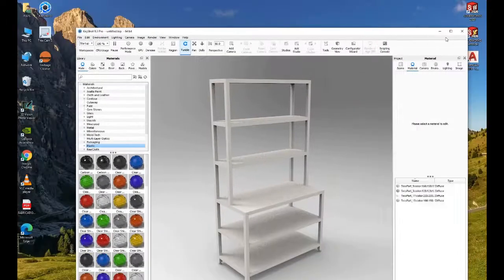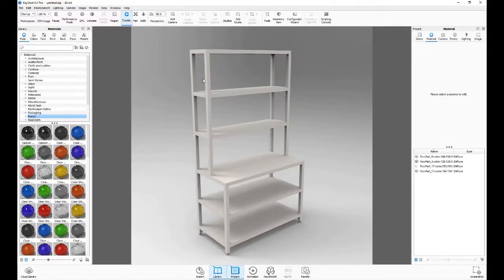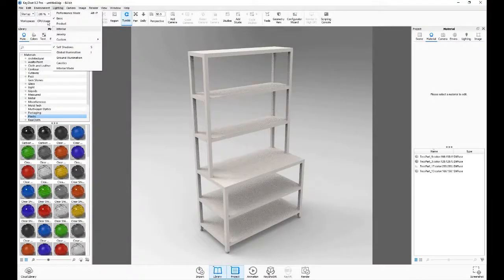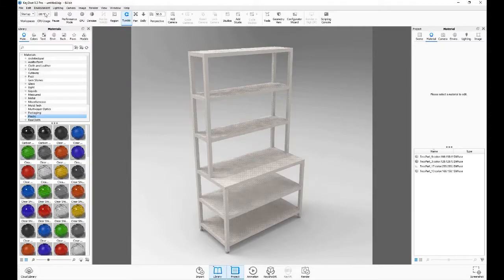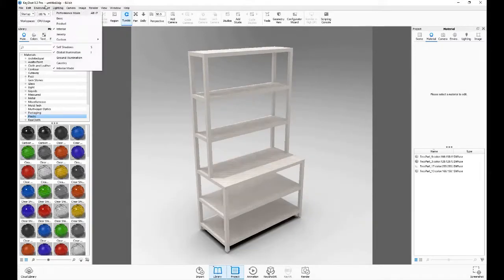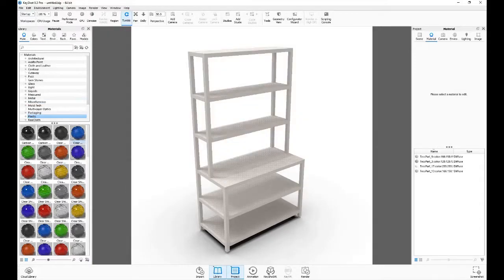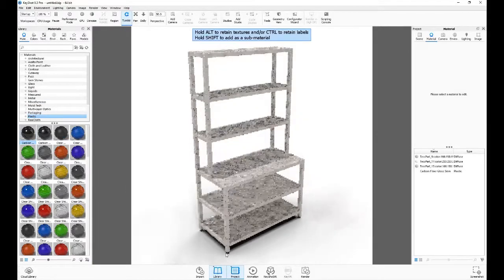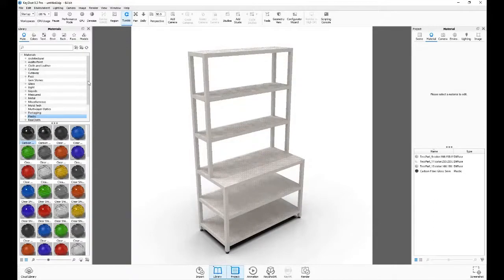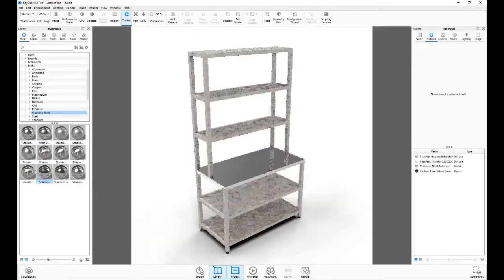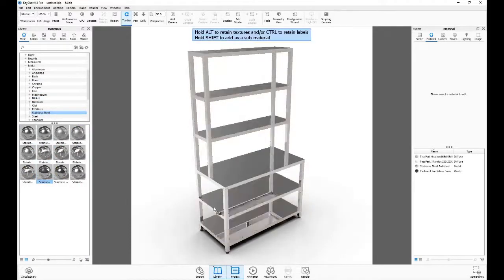So we need to add another one. This one is going to be the opening height. This one I'm going to get a little fancy. I'm going to say it's a spin button. So this gives me a minimum value of 1500 and a maximum value of 2500, and then I can tell it what the incremental value is. So I'm going to do 50. So we'll go ahead and say next.